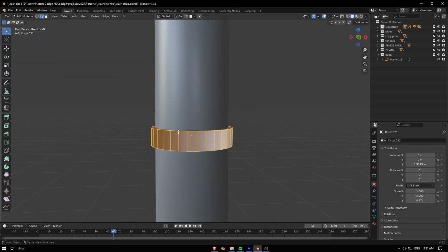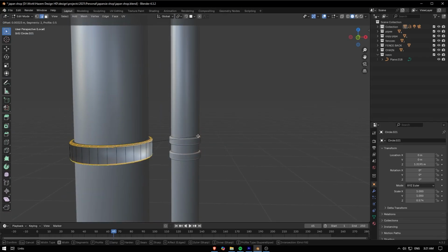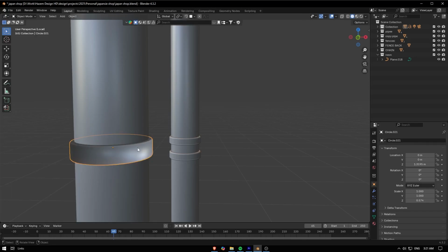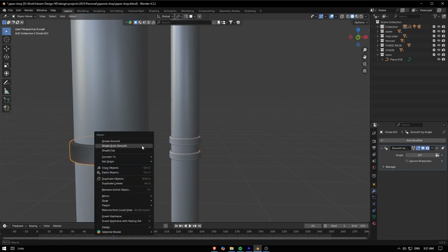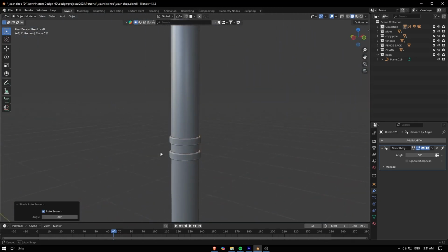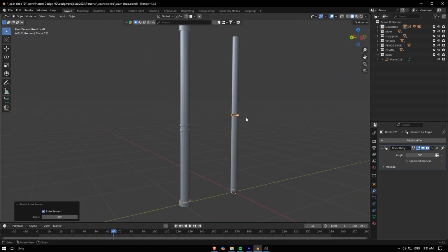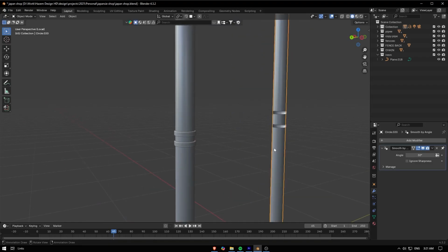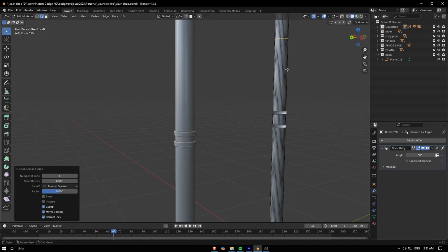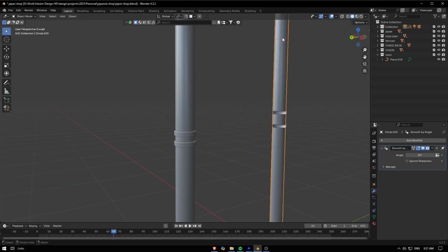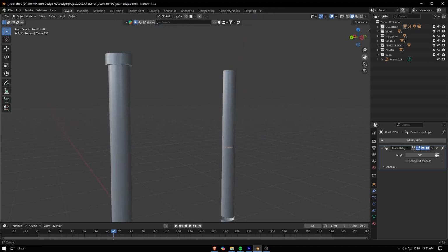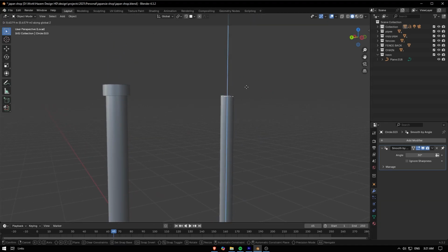And also I can bevel this edges here to give like some variation or some details, something close to this. You're gonna see the difference, this one. So I'm gonna copy this one, maybe Alt D, and drag one down. And at the bottom, it's the same story here. You go with one loop cut, Shift D, and B to separate it. And go like this, boost it to the top.